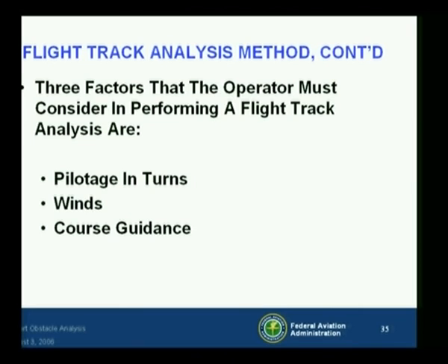The operator should consider the ability of a pilot to initiate and maintain a desired speed and bank angle in a turn. This is where simulation and testing come into effect. Winds are extremely important in the flight track analysis method because it tends to give you some tighter approach clearance capability. But when using the flight track analysis method, operators should take into account winds that may cause the airplane to drift off the intended track.